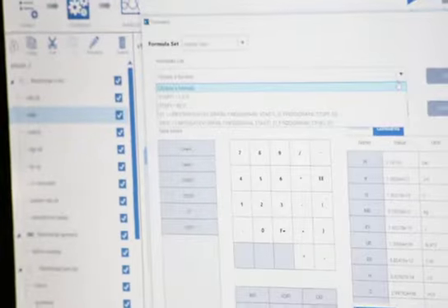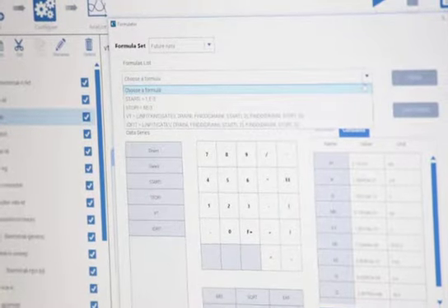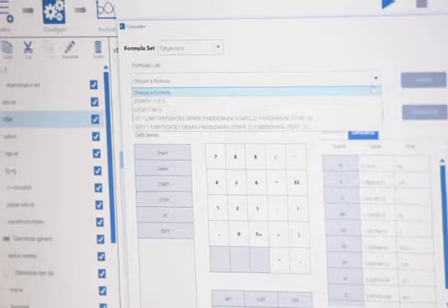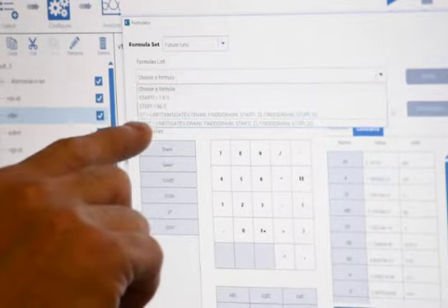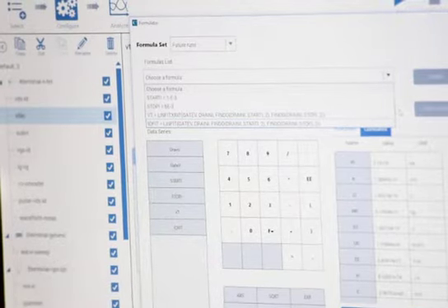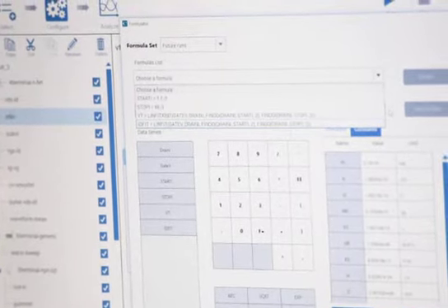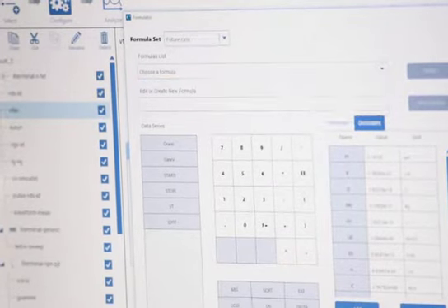So for instance, this V threshold is finding where the device breaks, and you'd have to go through the manual to understand all the commands. In the manual it has all this stuff defined, pretty easy. And then this is a line fit. You see, it kind of makes sense. At a certain drain current you put a cursor, and at another drain current another cursor, and you find the slope between them, things like that. So that's pretty cool.